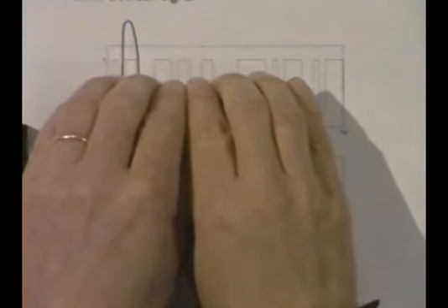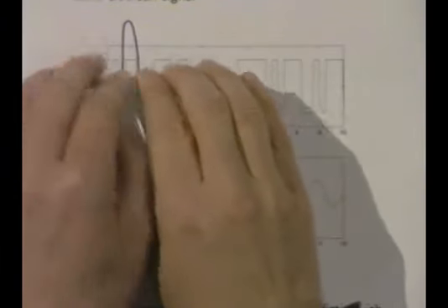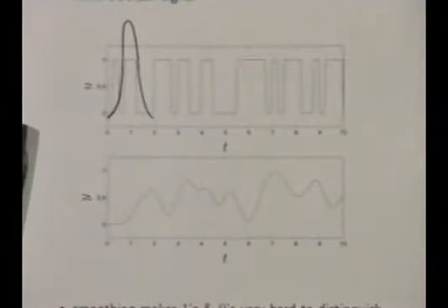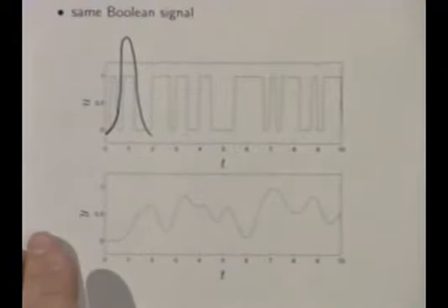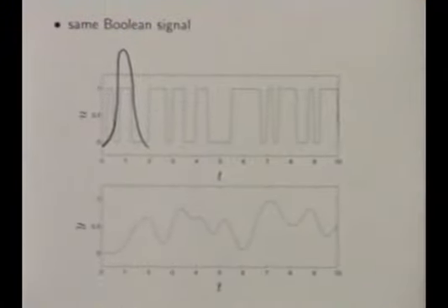Is there a question? If the impulse response was a delta function, would we be able to reproduce the signal perfectly? Absolutely. If it were a delta function, what would come out here would be simply this signal delayed by whatever that delay is, perfectly. The edges would not be ruined. It would simply be delayed. Then, of course, you'd be able to reconstruct the signal perfectly, because it's just shifted in time. So this is sort of the idea, and it gives you a rough idea.